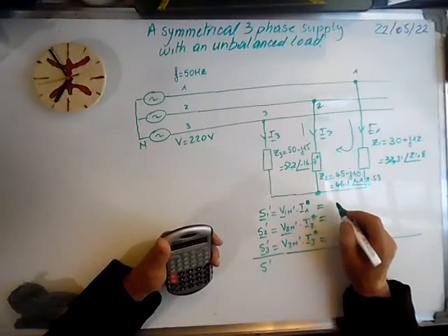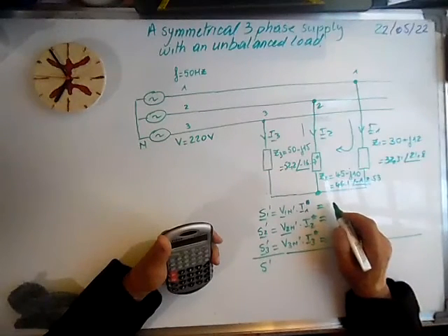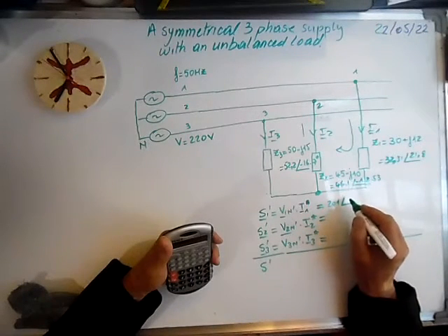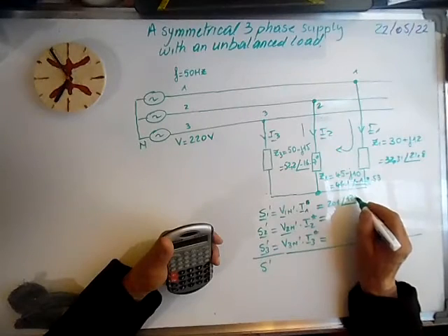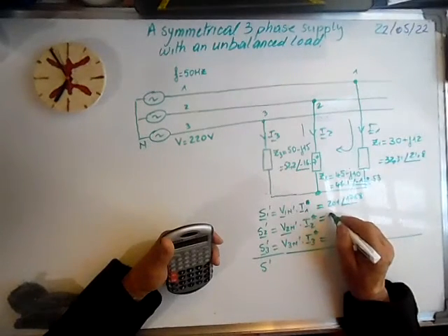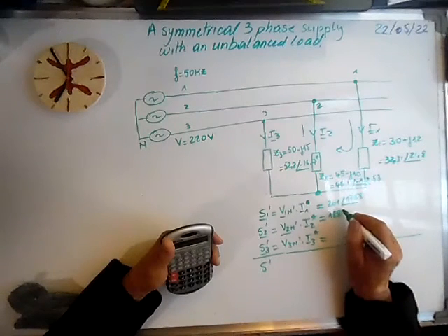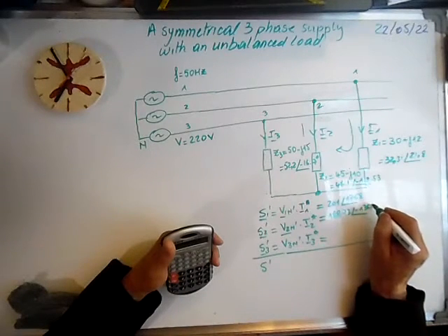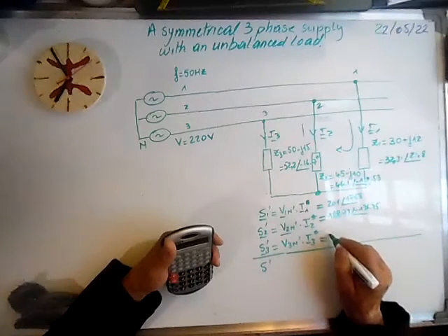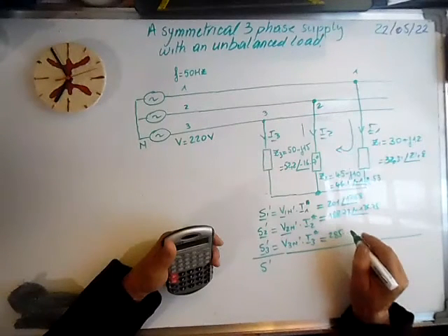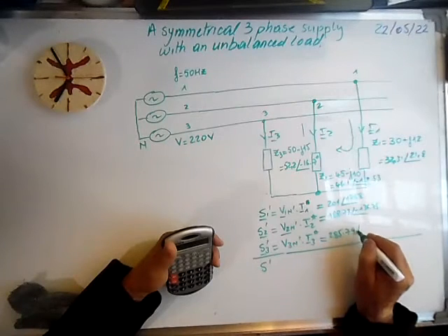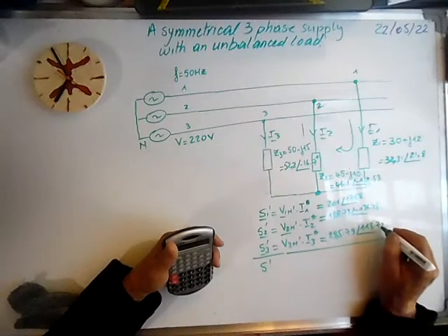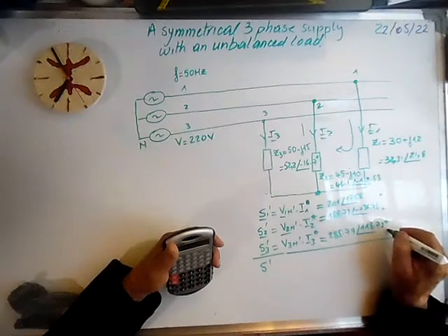Okay, so here we have V1N', the magnitude is 17.58, here is 188.73, argument minus 136.75, here it's 285.79, argument was 118.72 degrees, times the conjugate of the three currents.